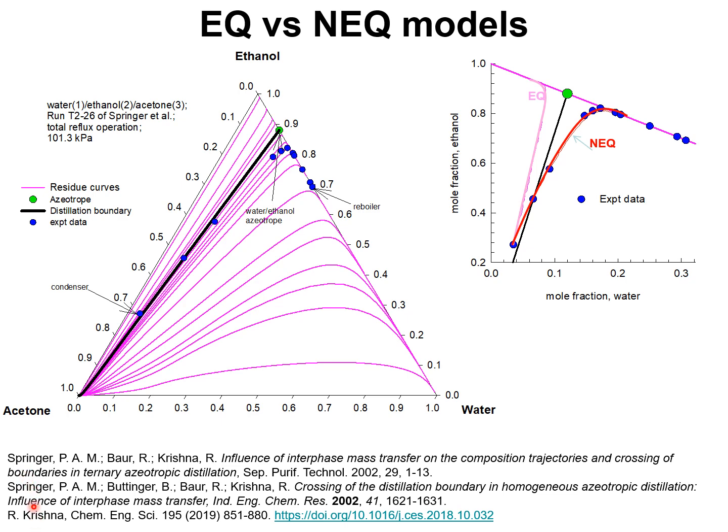The important message to emerge from this presentation is that for modeling azeotropic distillation columns, the use of non-equilibrium models with Maxwell-Stefan diffusion formulations is of vital importance.